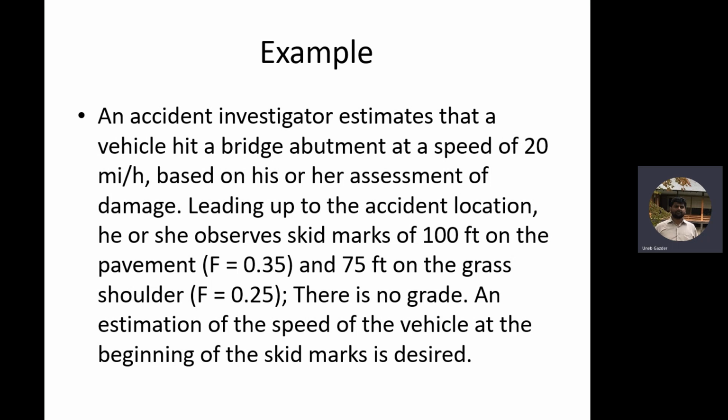Those are skid marks. Skid marks only happen when the driver was braking, so they are an indication that the driver was braking for this much distance. If you can measure how long the skid marks were, you know for how long he was braking, in terms of distance.